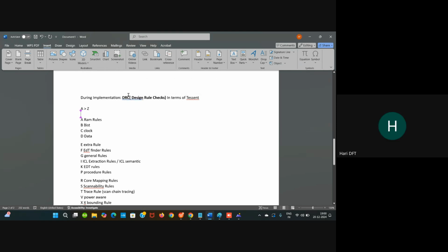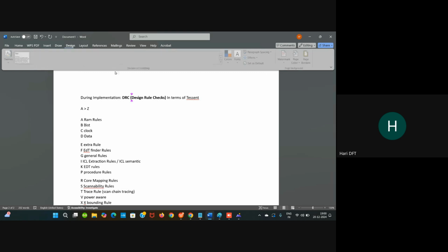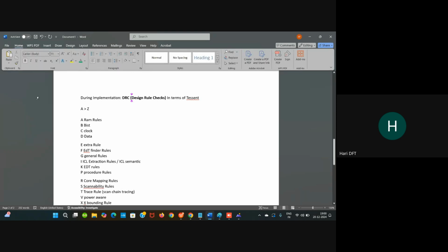Any rule that violates the design criteria. Our design consists of clock signals, resets, and data. If a connection goes wrong, or there is any unconnected net or unconnected wire in the design, the tool ends up throwing some DRC.